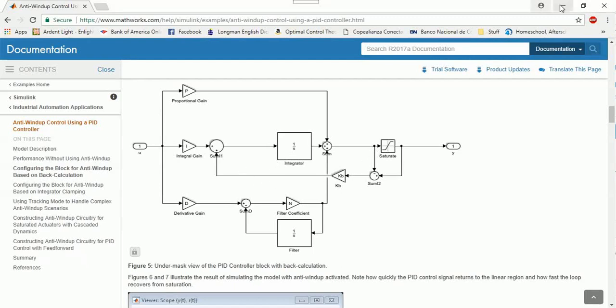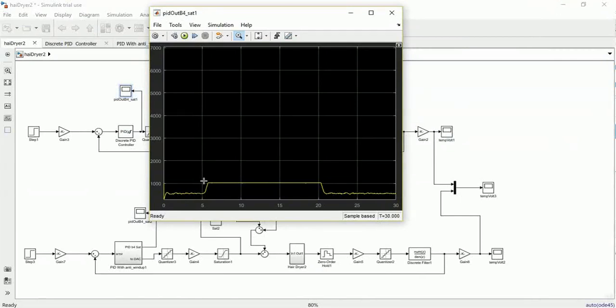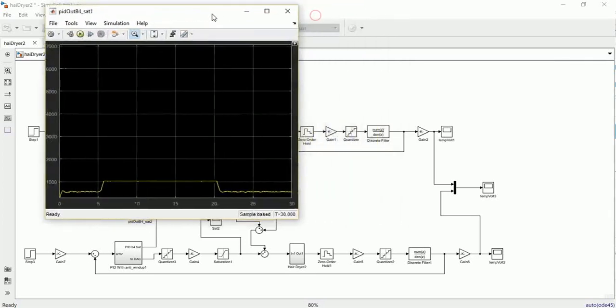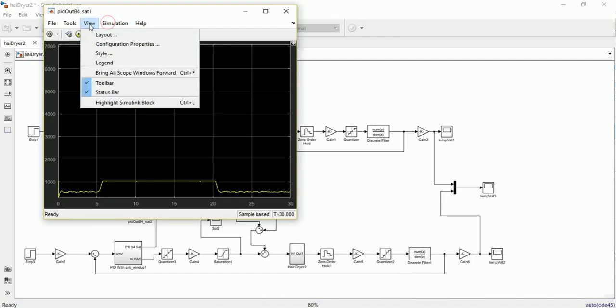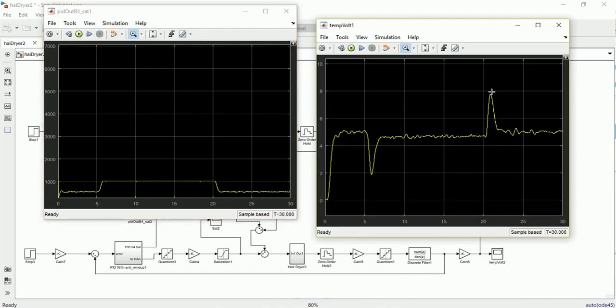So unfortunately this doesn't tell us the real accumulation of the integrator. This is just the output of the saturation. So this doesn't give us meaningful information. But the good thing is that we improved the transient response thanks to the anti-windup present in Matlab, based on the book of Astrom, Advanced PID.